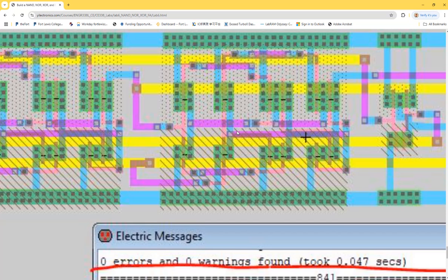This one is fine, but let's see if, for example, this guy, all right? And you see the gate, the poly layer, the pink one comes out. I can directly use, if I'm lazy, I can directly just use a poly and make the connections to all the places. You can see even from here to here, the two gates are shorted together. I don't even want to use just pure poly. See what I'm doing here?